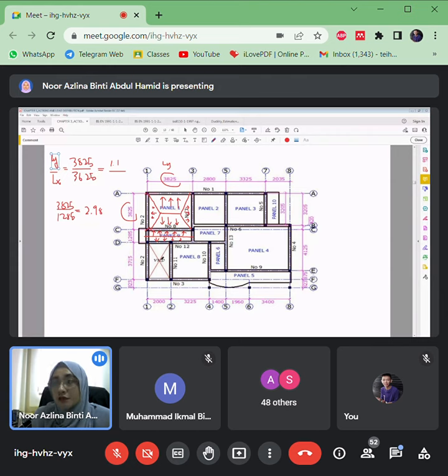Okay, for the void, there's no slab here. So that means this beam only carries its own self weight, or might have brick on it. There's no slab. This beam can be designed as a rectangular beam. Do you see the example of the rectangular beam? This beam has to be designed, if it is connected to the others, as a T section here. Okay, if I cut here, it has to be a flanged beam because there's a triangle load that is transferred onto it.